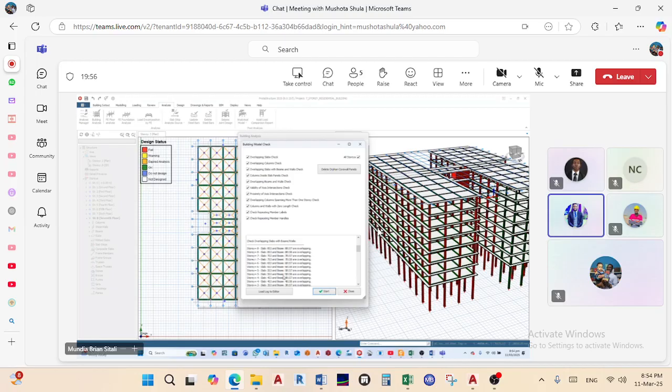Then these ones, it's the same thing. So I don't want us to waste so much time sorting out these errors. But once I show how I sort out these two, then we come back to check the building model. You'll be able to see that what's happening is just that we have modeled the slab and it's crossing the space where the beam is running. So that is recognized as an overlapping.